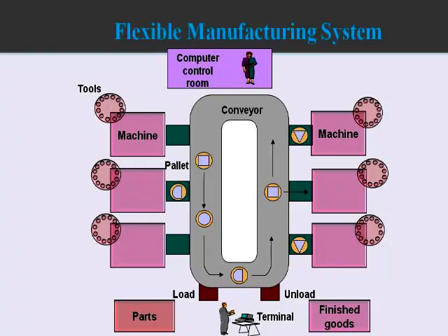Pallets are automatically placed with automatic setup dock pins. The pallets will be located on the machine. So as and when a particular part is loaded on a machine, the part will be read, and accordingly the program for that part is loaded, and the machine starts processing that program. This goes on.